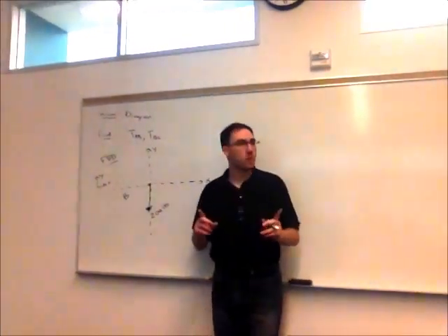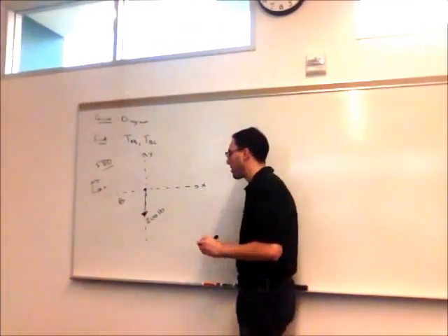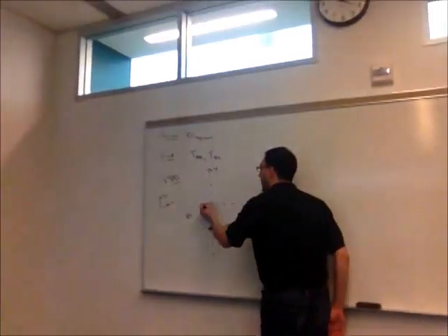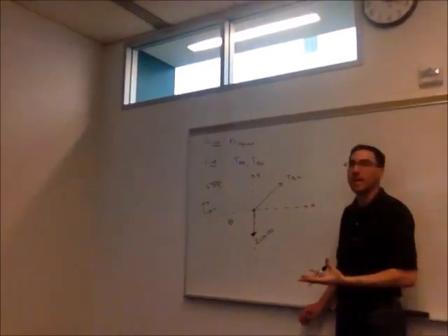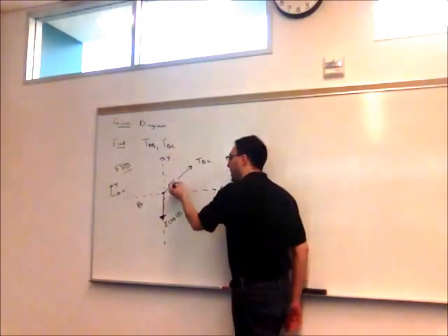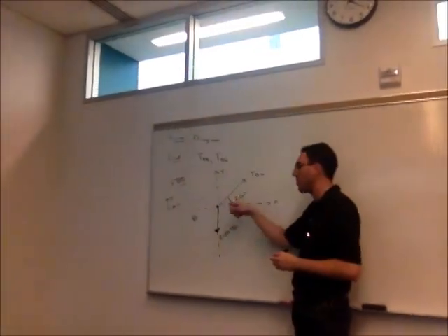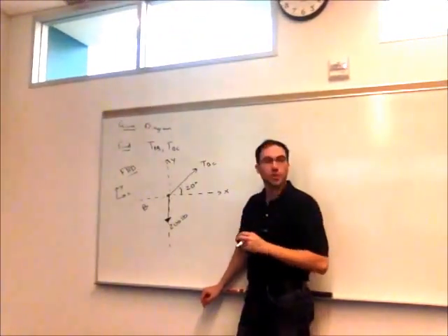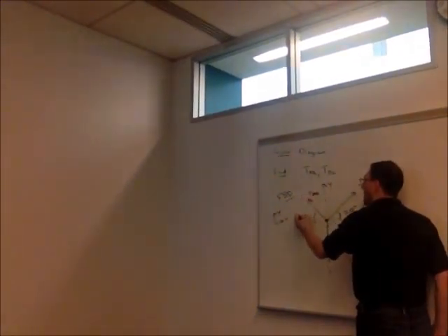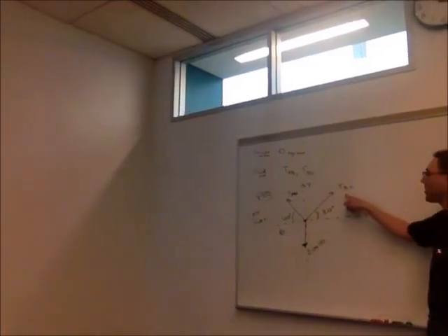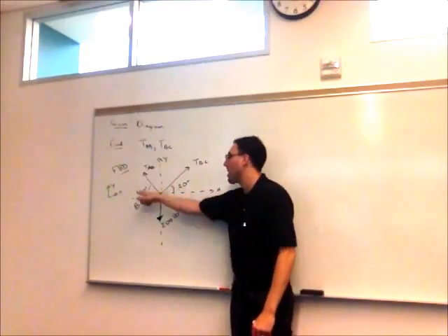Right, so we know that forces in ropes and cables always act along those ropes and cables. So when we cut away rope BC, we'll replace it with the force that rope exerted on the particle, which I'll call TBC. I know it has to be a tension because this rope can only exert a tension. It can only pull on objects, it cannot push on them. And we know that it's directed along that rope, so it's also at 20 degrees. Same is true for AB. It has to act along rope AB, so it has to act along 40 degrees. I don't know what the force in these cables is. That's why I'm labeling it as a variable, but I do know their direction.